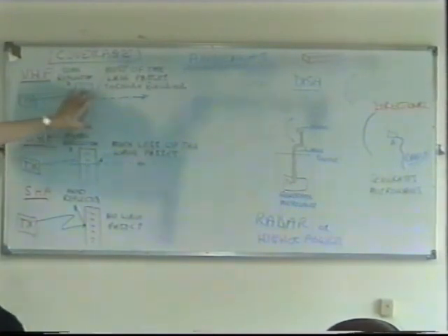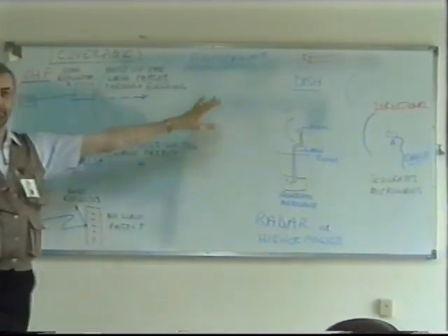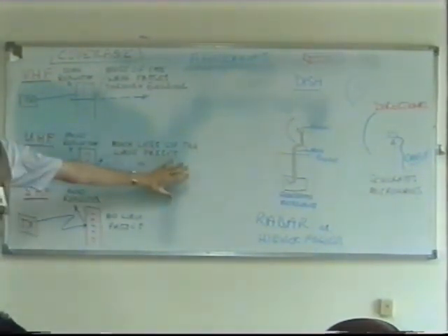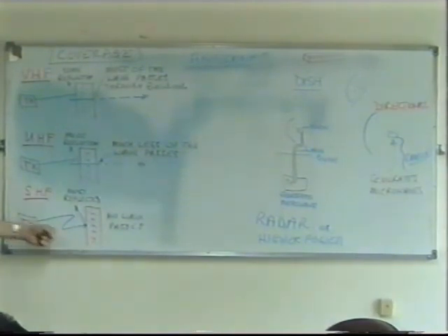If there's a couple of buildings, then VHF will probably work. If there's maybe only one building or low-level terrain, then this might work. If there's anything at all between you and your receiver here, it will not work. Anything. Even a bird flying in front of your antenna would momentarily destroy it.